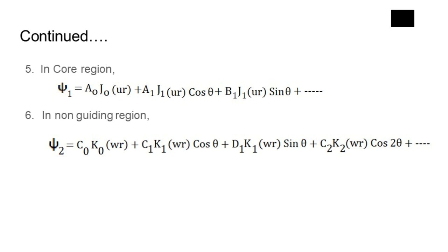So after that, for example, in this case, we get the 56 equations. So this is for the field equations. In these 56 equations, we can accumulate 56 unknown constants A, B, C, and D to ensure reasonable accuracy. To obtain the non-trivial solution of the set of 56 equations, the determinant formed by the coefficients of the 56 unknown parameters must be set equal to 0.